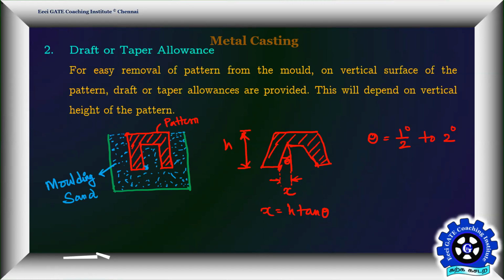Sir, in the numerical thing, for pattern only, it compensates solidification process. Sorry, only solid, not solidification. Sprue will compensate the liquid loss, not sprue, it is riser. Riser compensates liquid and solidification, both. Yes, sir, that only. When I discuss the riser, you'll clearly understand why the riser is compensating and all. We'll get that point.